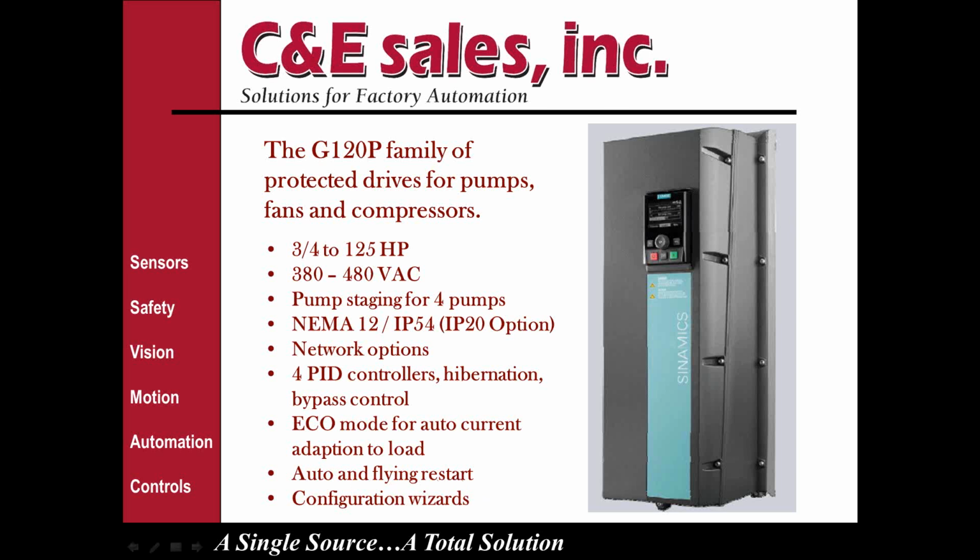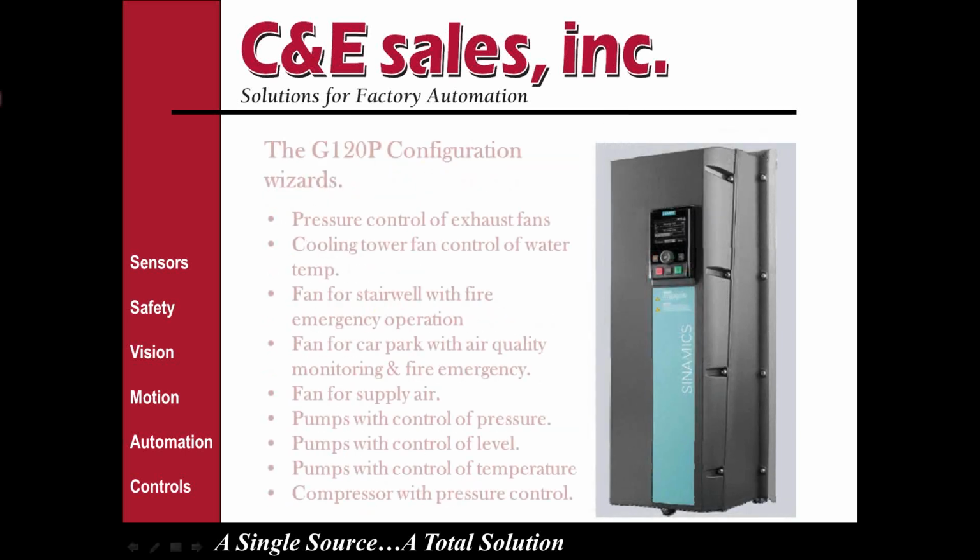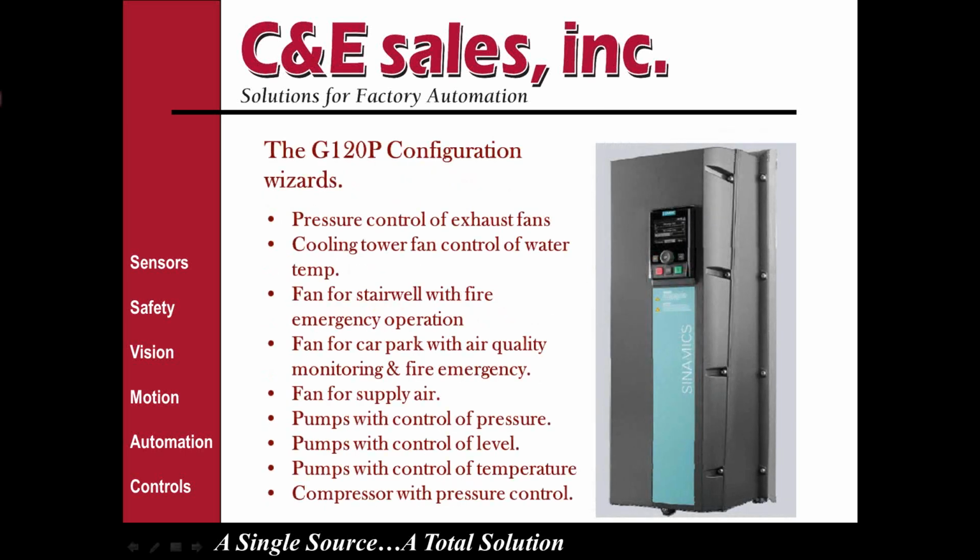And like the rest of the systems, they are available with configuration wizards to help you through the selection of any given application. Here are some of the wizards, most of the wizards, not all of them. You have pressure control for exhaust fans, so you can set up to maintain a constant pressure in exhaust. And the same with cooling tower fans for controlling water temperature. So you can control the fan speed on a cooling tower to adapt to changes in the water that's being cooled coming through the system.